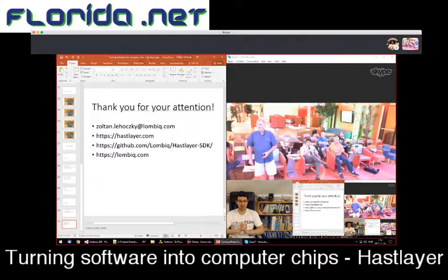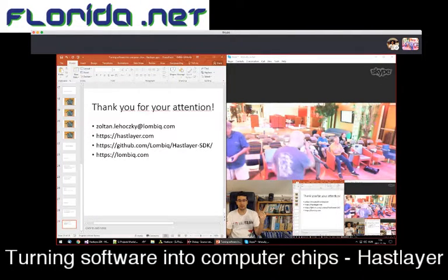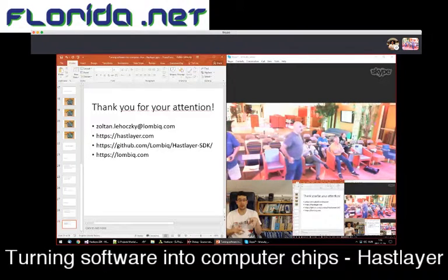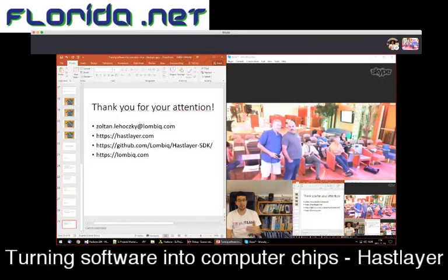Yeah, that's quite observant. Indeed, we have a constant for how many tasks there will be. The short answer is that since we won't run that code on a CPU that can dynamically fetch anything from the memory, but rather we will hardwire all of this logic onto a chip, you can't use some kinds of dynamism. For example, the level of parallelism, basically the number of tasks, should be compile-time defined, because that many instances will be wired onto the FPGA, so that can't be dynamic.